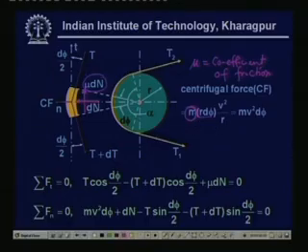What is happening? This is basically the mass of a belt of unit cross section, that is the belt mass. This is the belt mass for a 1 meter length, suppose. So, this is what we get as m, and r d phi is the length of the belt, giving the total mass of the belt, and v square by r.